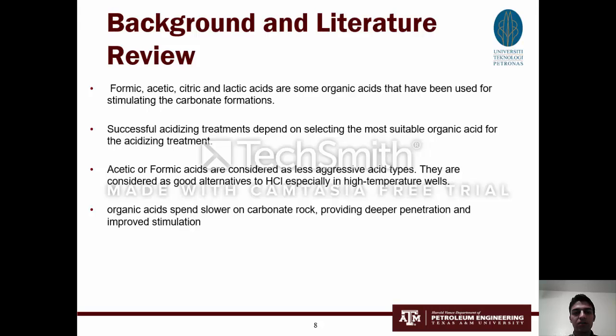Successful acidizing treatment depends on selecting the most suitable organic acid for the treatment. Acetic or formic acids are considered less aggressive acid types. They are considered a good alternative to HCl, especially in high temperature wells. Organic acids spend slower on carbonate rock, providing deeper penetration and improved stimulation.